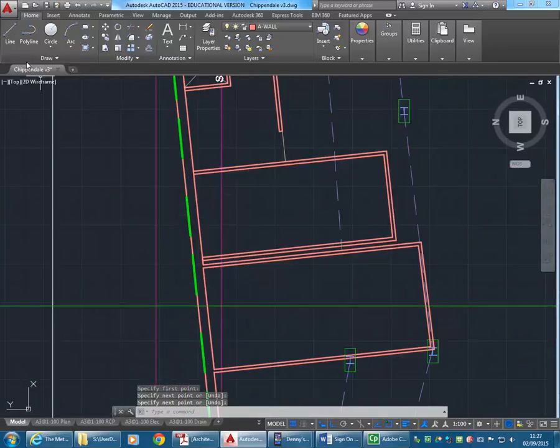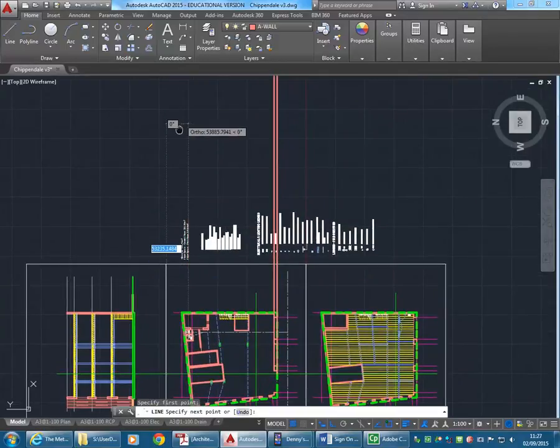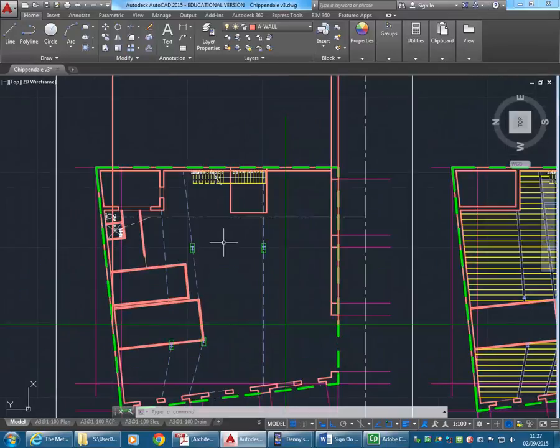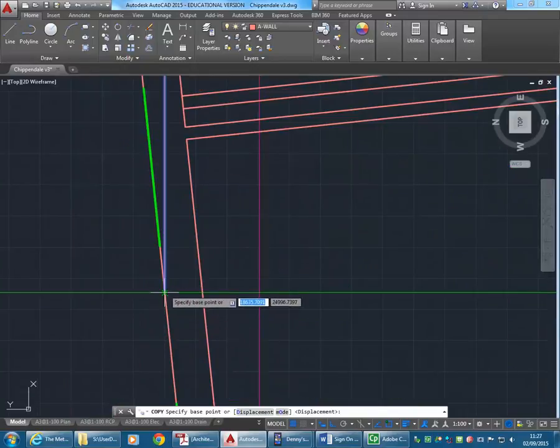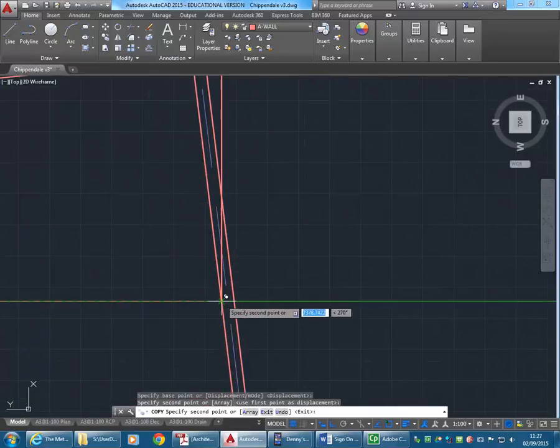On the other side of the building, this time I can just project from the intersections of the wall and my section line. It's looking at right angles to the other one, at the stairs. And a good trick there is to copy that line rather than just drawing it with the line command over and over again. You can select it, click copy, zoom in and pick it up at the base, and then just snap onto each intersection where it cuts through a wall.